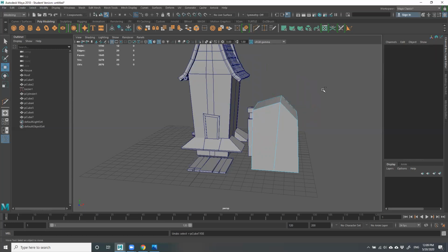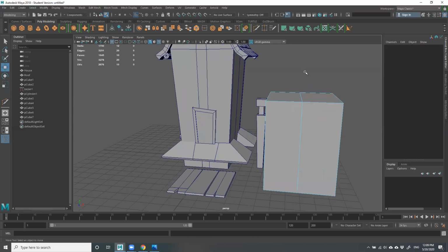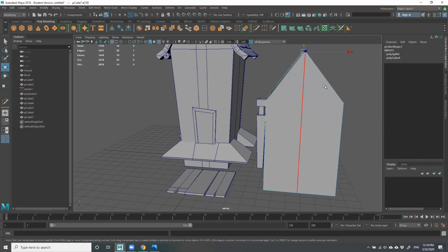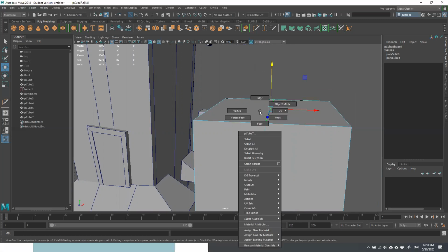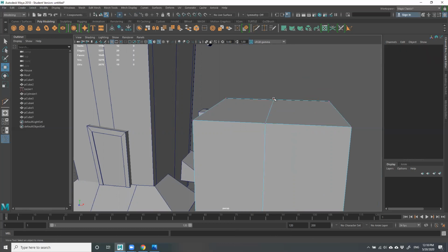Now a different way, and maybe a better way, I think this would be easier, would be to take, say, the edge, right? Move that up. That way I didn't have to do as much work to manipulate it here. Or I can take the vertices. This edge is made up by this vertex and this vertex. So if you select this, and then shift select this, you see when I press shift, this little cursor becomes a little plus sign, and I can do that.